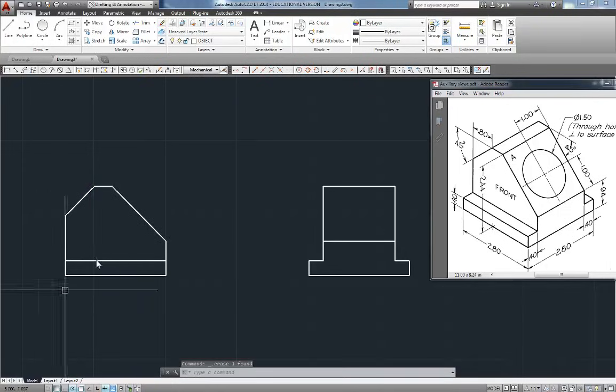Okay, I have all the geometry I can produce at this moment in time here in the front view, and I'm ready to start my auxiliary view. Now, to do that, we're going to project from this slanted surface perpendicular to that surface out into space in this direction. And we're going to use a tool that's actually more used for drawing in 3D in AutoCAD to make this really easy to do. All right? So you'll get this in lecture, but here you go.